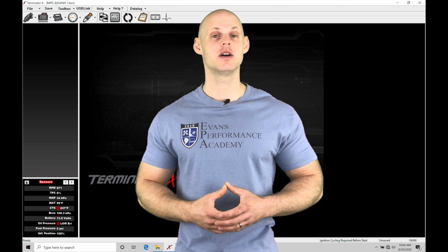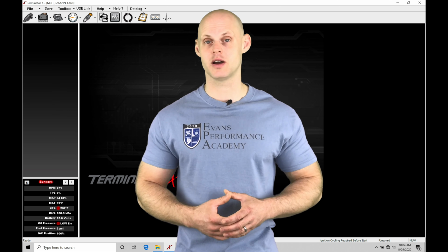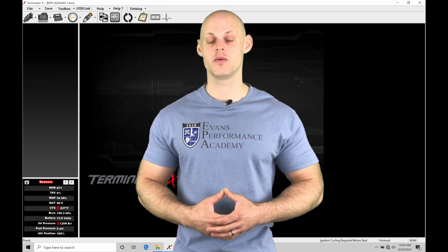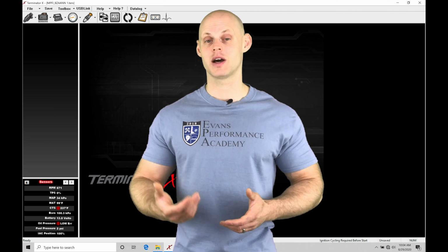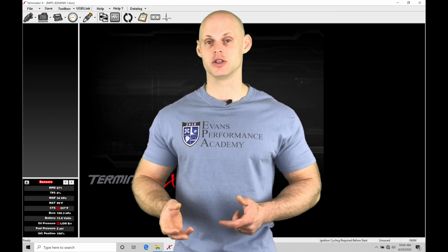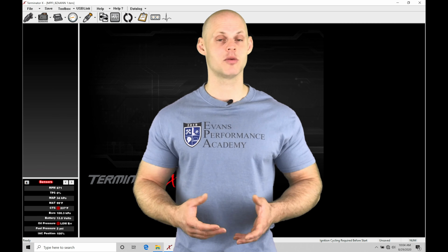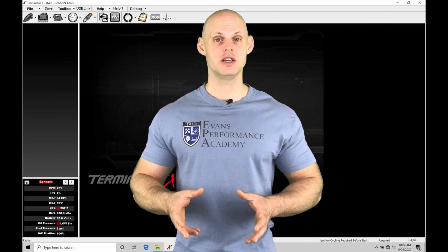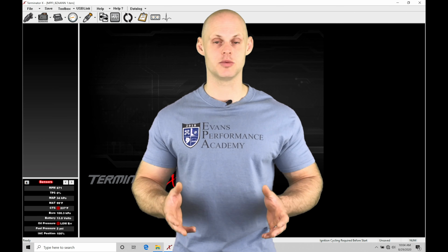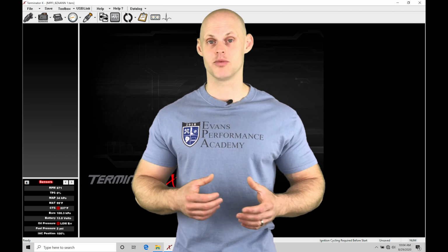In this video, we're going to take a look at some of our advanced fuel and spark timing tuning that we have available in our Holley Terminator X software. If we want to make sure we have some kind of a correction per cylinder, we have individual cylinders that we can go in and adjust for fuel and spark timing within our software. We can take things a step further and implement three-dimensional tables per each cylinder and then correct based on a wide variety of conditions. There's going to be a huge amount of flexibility in our programming.